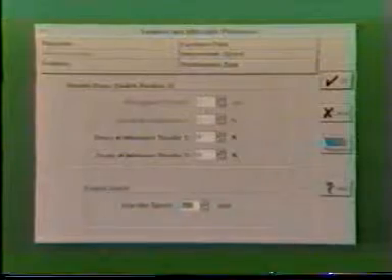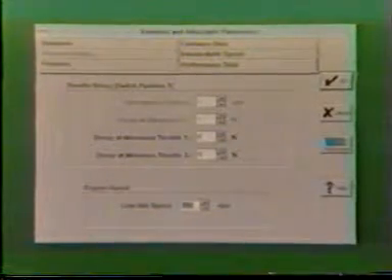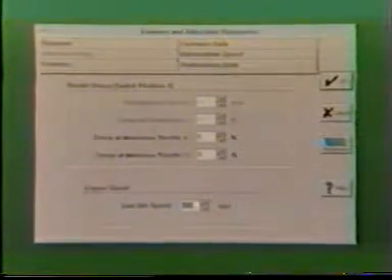The variable speed governor would also be selected from the Features screen in the Features and Adjustable Parameters function of Insight. In the Performance Data folder, the same parameters as were set for the Automotive Governor can also be set for the Variable Speed Governor.